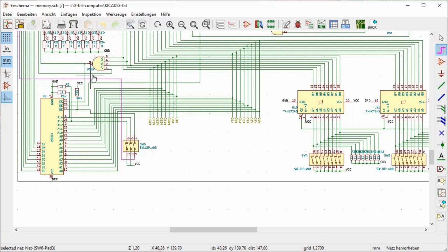This is the 4-input NAND gate that decides whether the RAM or the ROM chip is active. It gets as input the stack line and 3 of the address bus lines, which in this case are the highest lines that will trigger the chip select of the ROM chip.